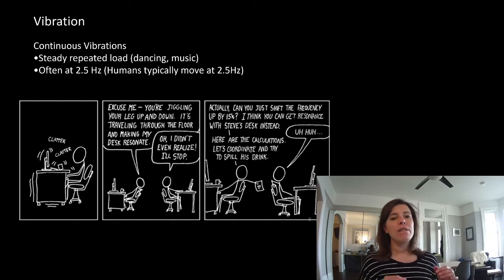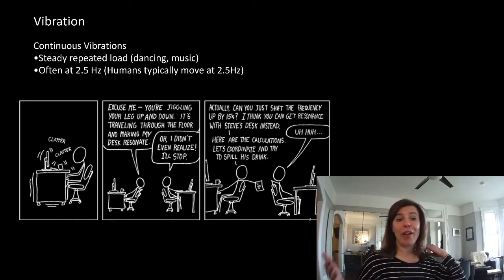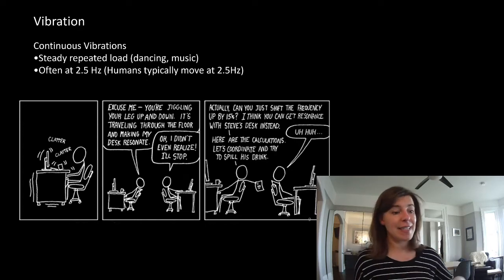Feature stairs, very susceptible to vibration. Footbridges, very susceptible to vibration. But we also have human ability to cope with it. On a footbridge, you kind of get that there will be some vibration. On a feature stair in a very fancy building, you don't want to feel it move at all. So your tolerance for vibration changes depending on your location. And we have to, as engineers, appreciate that. And so there are varying criteria depending on things exactly like that.